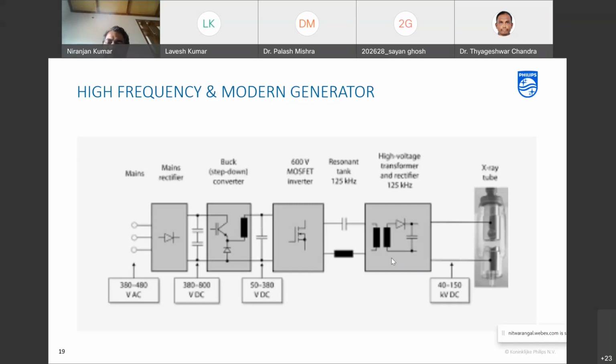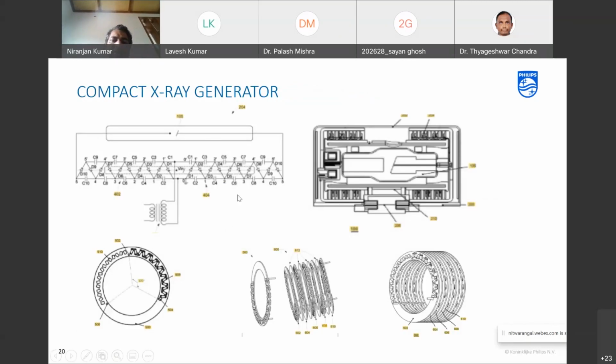Okay, a couple of examples I just gave. This is one of my patents, a compact X-ray radiation source. This is not the innovation as such, but as an engineer, it's not only the electronic circuit. How you package it matters too. This is called a ring multiplier. From the high frequency AC, I can either generate the 150 kV here, or reduce it to something like 5 to 6 kV. This is very compact, and it is just diodes and capacitors, which multiply. Every stage multiplies by 2.